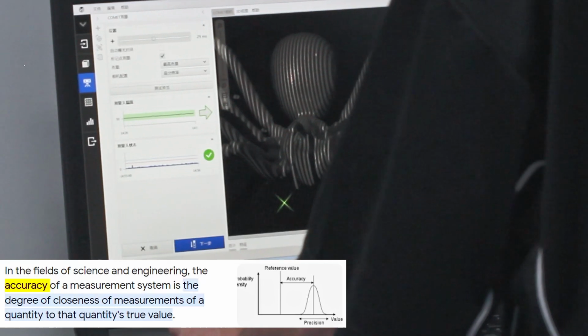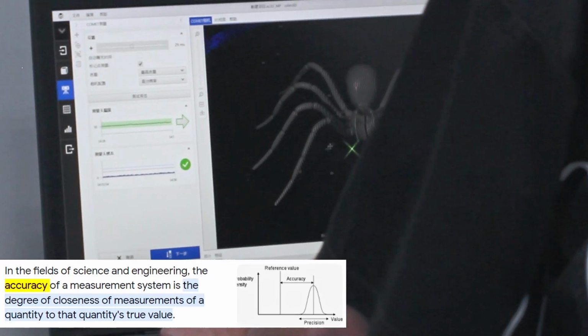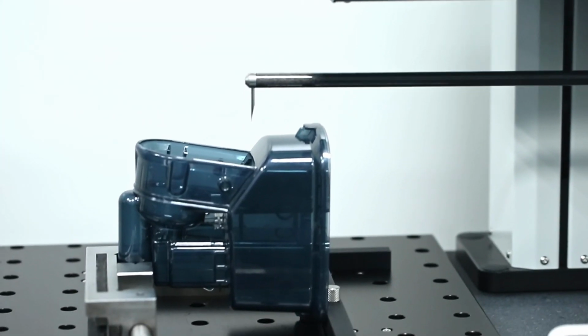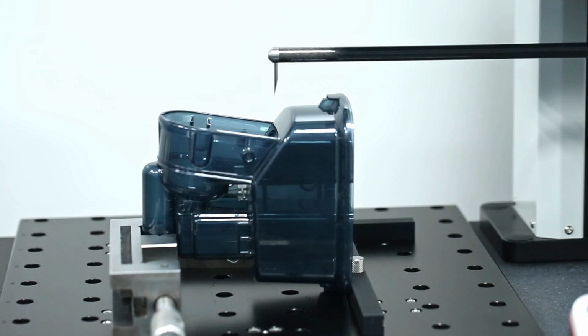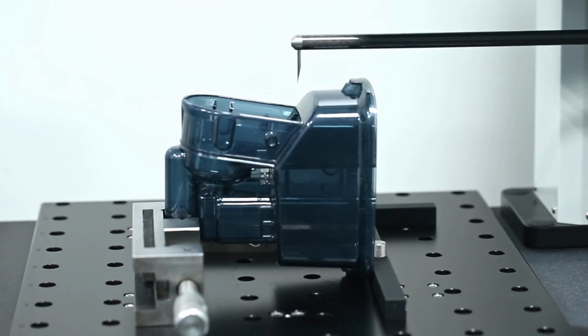First up, let's talk about accuracy. We define it as how closely a result comes to being equal to the ideal or the standard. For example, if we want to make something that's exactly 1 meter long, the first thing to do is to machine it very well. Then, we measure the object as carefully as we can against a known and recognized standard.